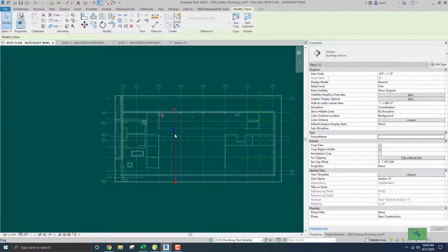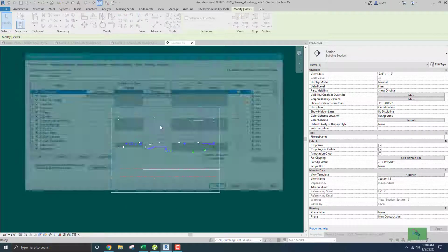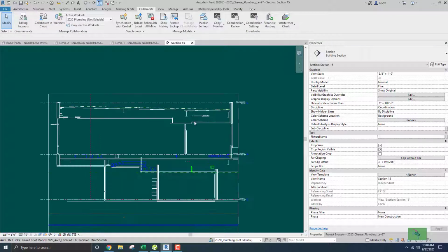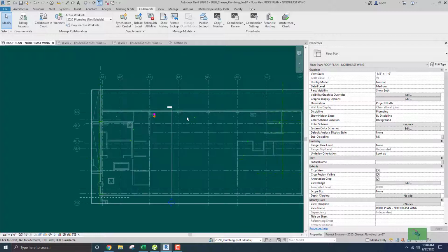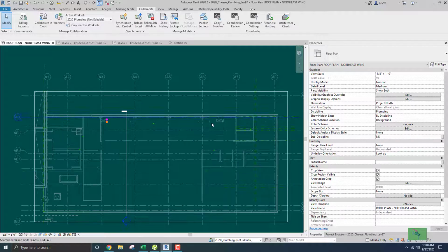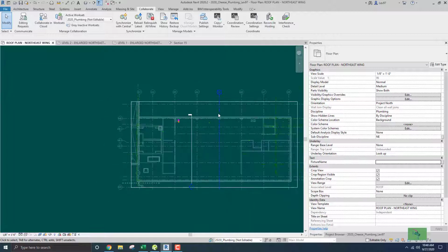It's going to take a little bit of this guy and look at that section, and turn on my architect's drawing, and we can see that it's sloping from left to right, which is my north to south, right? North to south. Okay, there's going to be 2 sets, one set here, and there's going to be another set here. So I'm going to divide this roof in half, right? So let's do it.